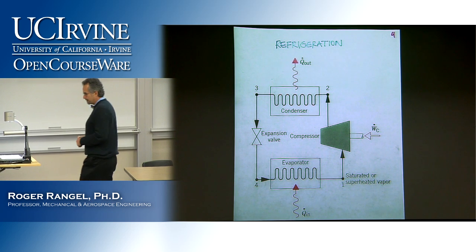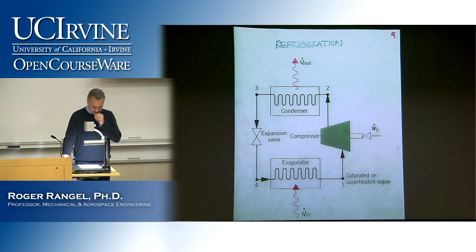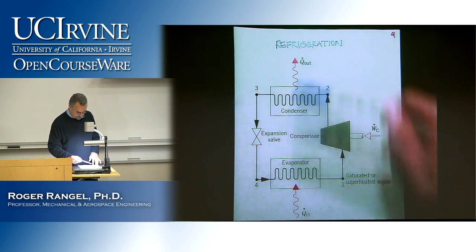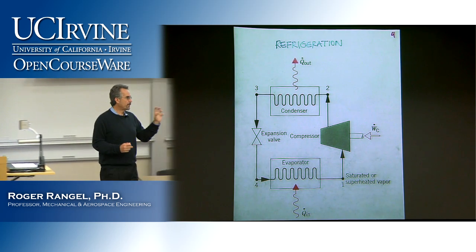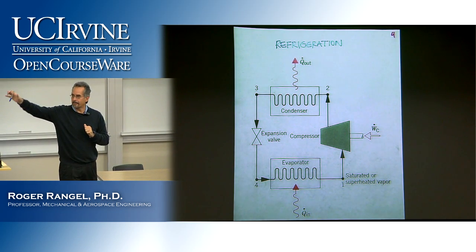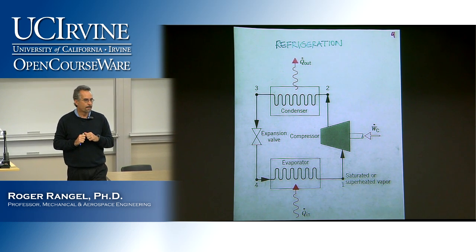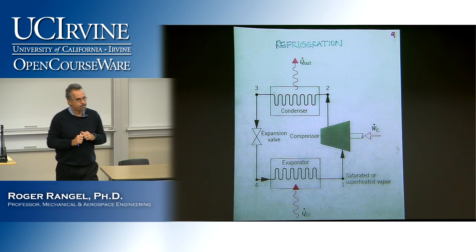Whatever room the refrigerator is located. So that's where that heat is going to. Are these the same, you think? So whatever heat I take out of the refrigerated compartment, is that the heat that goes down into the room? Why not? It also includes heat that's a byproduct of the pump system.